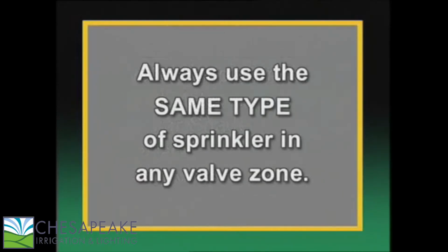The rule is, always use the same type of sprinklers in any valve zone. Keep sprays with sprays, rotors with rotors, and drip irrigation with drip.